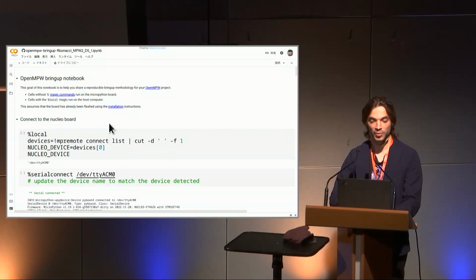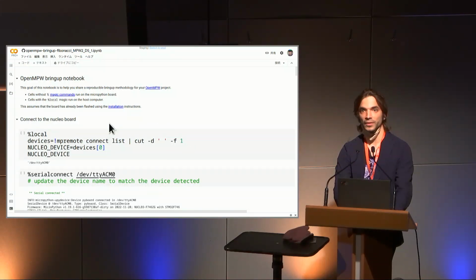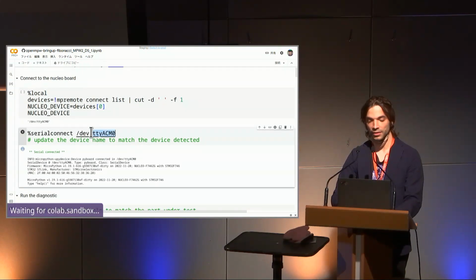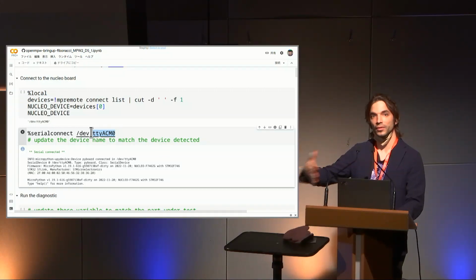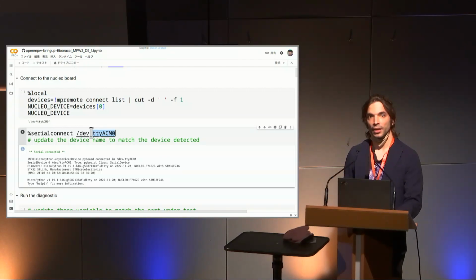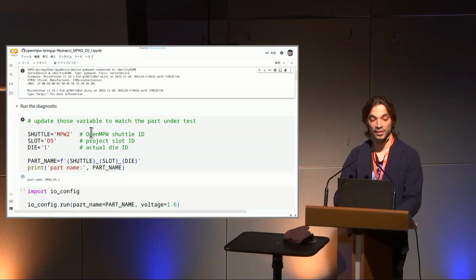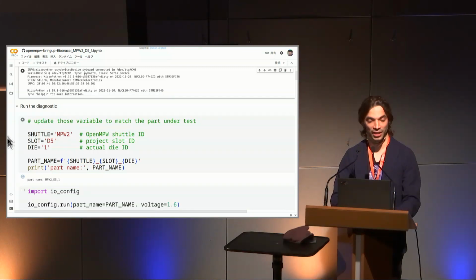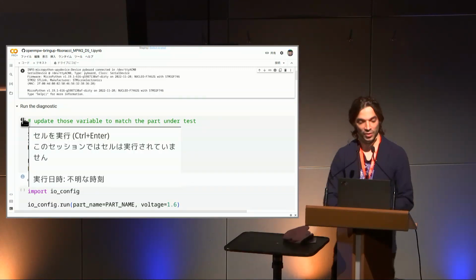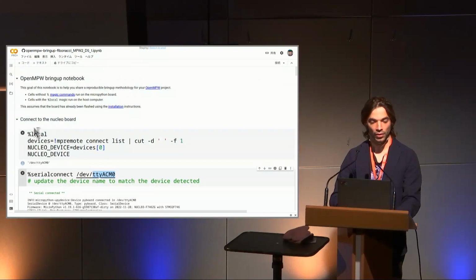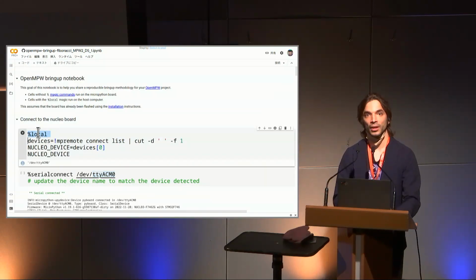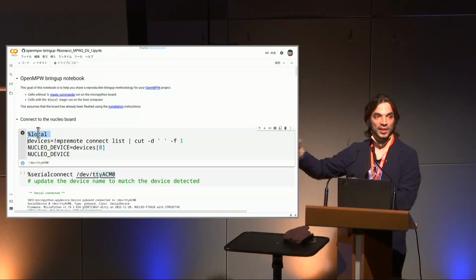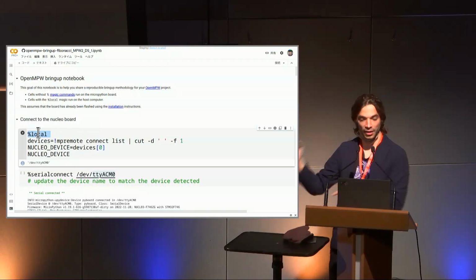And I found a very nice module called ipydevice that's really great for doing this kind of work, so I just wanted to give a shout out to it here. It allows you to connect to the serial port over a board that's running MicroPython, and then it allows you to send cells for execution directly on the device itself. So rather than executing on your host, when I click play here, it executes on the device. And if I tag a cell with local, it runs on my host computer. So now I can have a single notebook that describes what needs to be run on my computer, in sequence, and what to be tested on the device, and I can validate something.